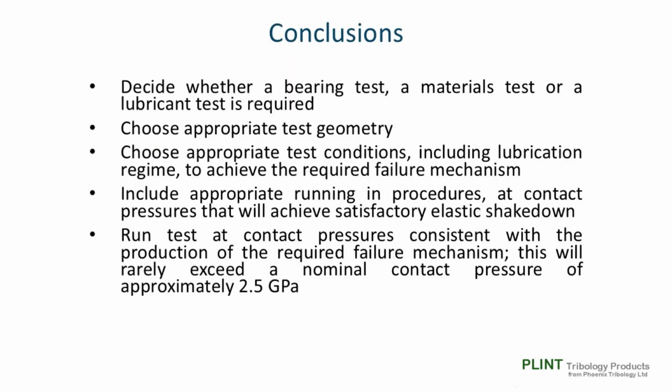So, to conclude, before we start, we need to decide whether we need a bearing test, a materials test, or a lubricant test. We then need to choose an appropriate test geometry and test conditions, paying particular attention to the lubrication regime under which our tests are going to be run, hence to achieve the required failure mechanism.